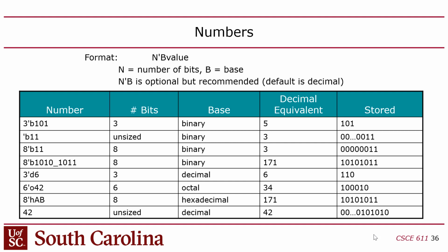There actually is in Verilog, the default is 32, but when you're doing Verilog design, you don't very commonly use 32-bit values. You might have a 1-bit or a 2-bit or a 3-bit or 5-bit or 9-bit value, right? So the problem is that if you have a scalar constant like 3, for instance, the compiler doesn't really know how to interpret that. How many bits are you talking? You say 3, but how many bits is that 3?